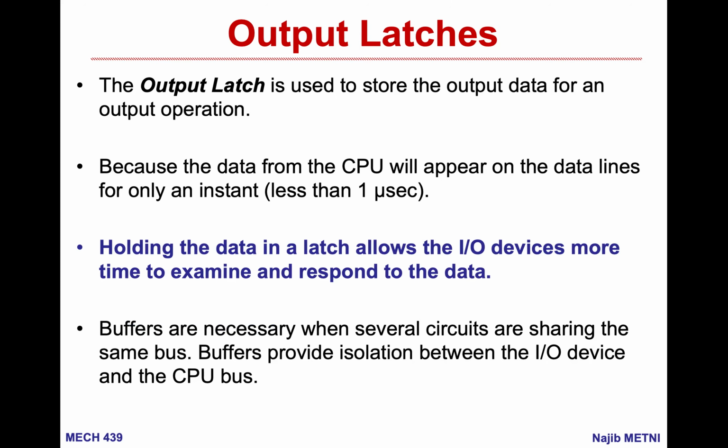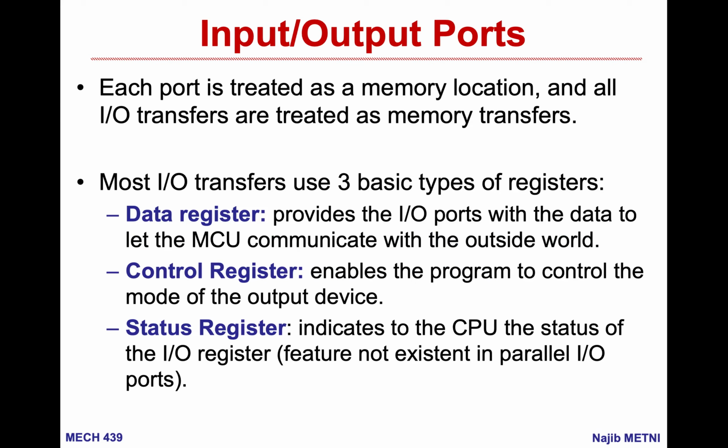So here I wanted to show you that for every pin there is a bit that will tell if this pin is an output or an input. If this bit is 1, I am saying that this pin is an output. So for example, if I have 3 bits and in the control register there is 0, 0, 1, I am saying that the first two pins are output, and the third pin is input.